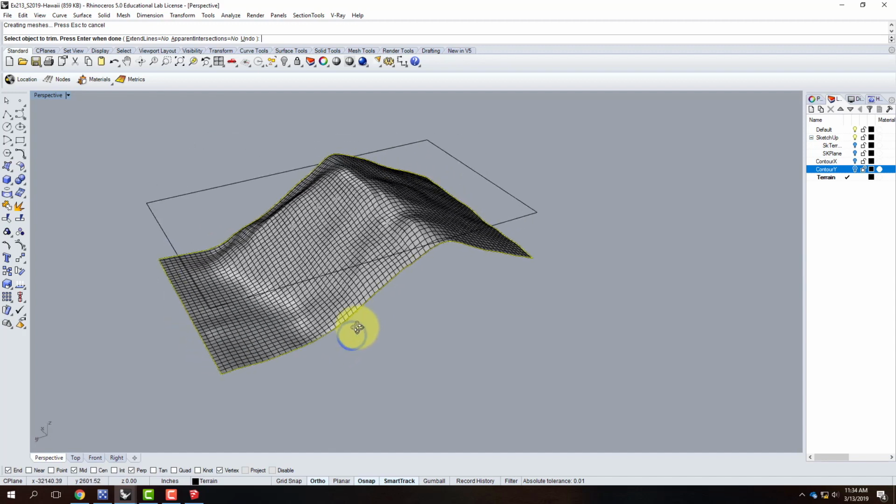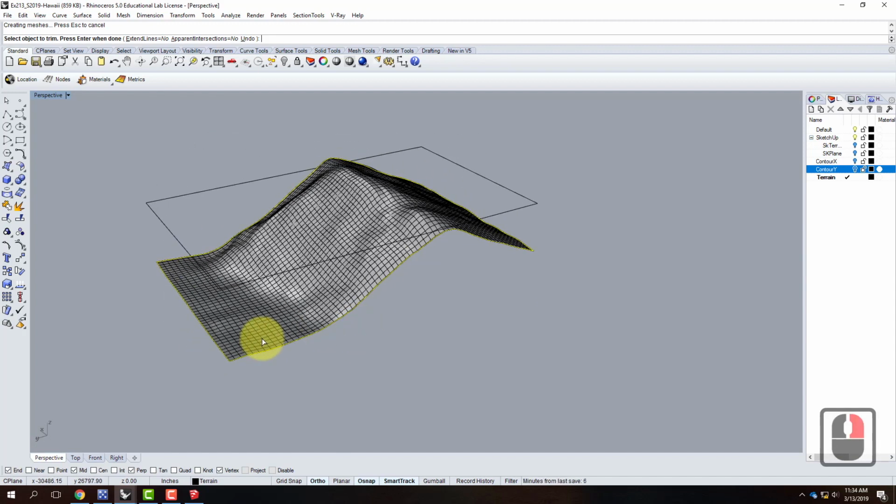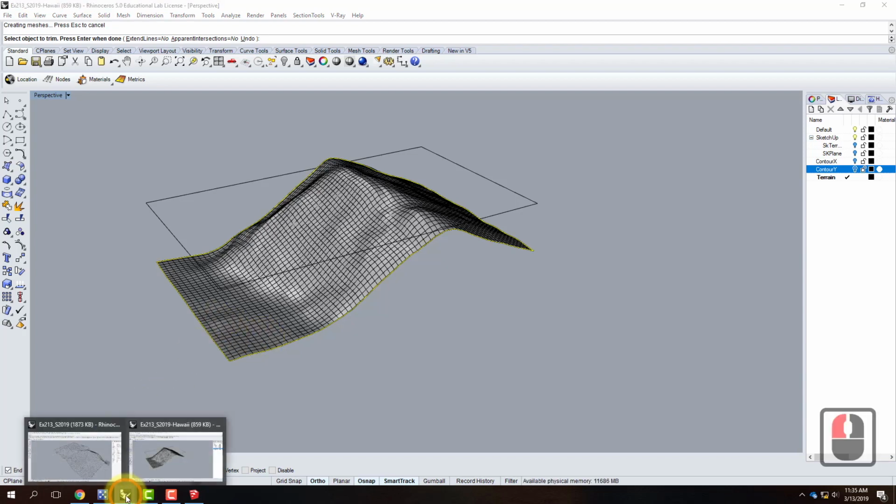The next piece of this is I need to know what intervals to cut my contours at, because I need to know the thickness of that material. So like I said last class, I'm going to suggest that you use the cardboard that's available at the bookstore. It's not that expensive, and it's readily available for us. It turns out the cardboard plus the little bit of glue that'll be in there is about 5/32 of an inch.